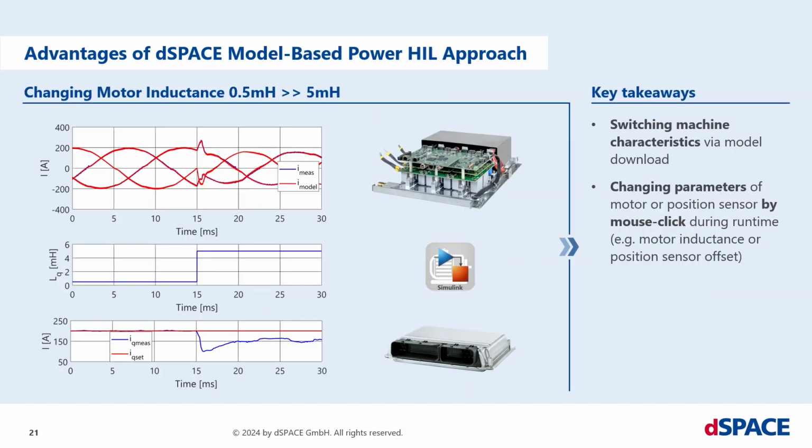There I also have some examples when it comes to the generator. You can test if your inverter is also valid to drive the generator when it comes to changes in machine parameters. This is just a theoretical task, but you can test these theoretical tasks at full power level. So for example, if the motor inductance changes from 0.5 millihenry towards 5 millihenry. That was done, you see it here in these measurement results.